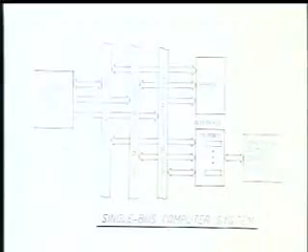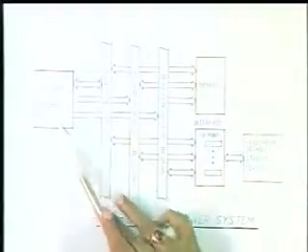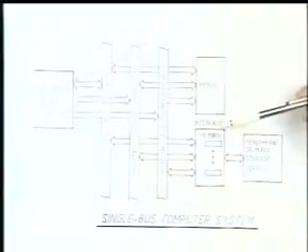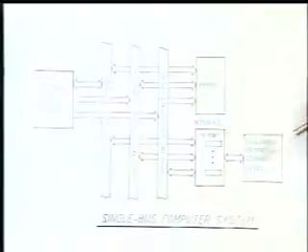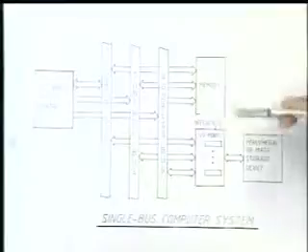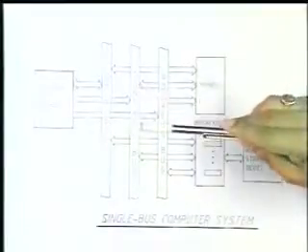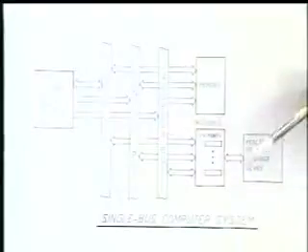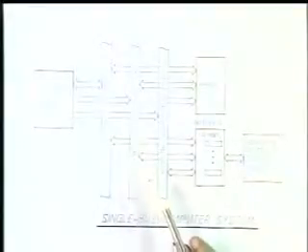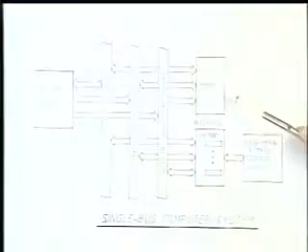Now, this is the central processing unit, which is communicating with the memory and the input-output devices, which are called the peripheral. And this is the interface unit or interface hardware, which communicates with the CPU and the memory. You see that the memory and input-output devices are connected to the CPU through three independent buses. One is called the data bus, another is called the address bus, and the third one is the control bus. Now, you appreciate that the address bus is required because one has to give a unique address to the memory in order to access a particular data or parameter.